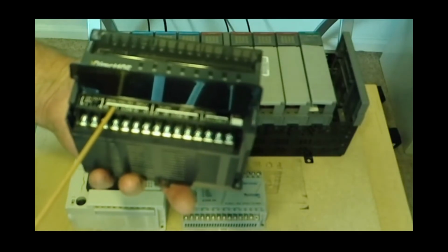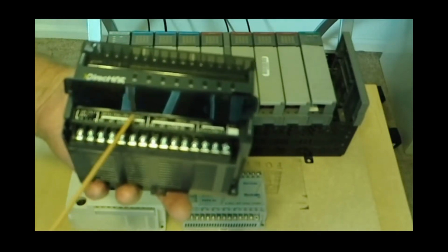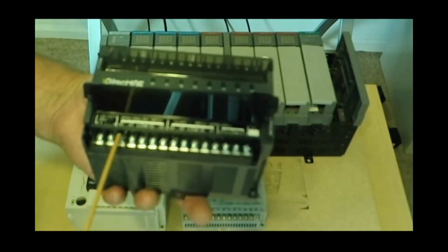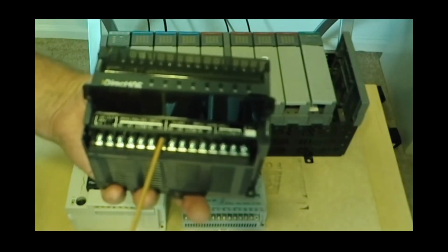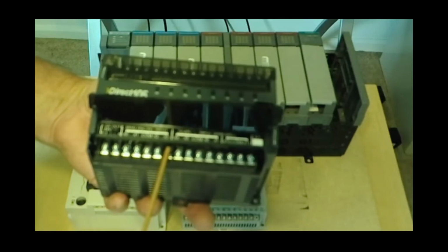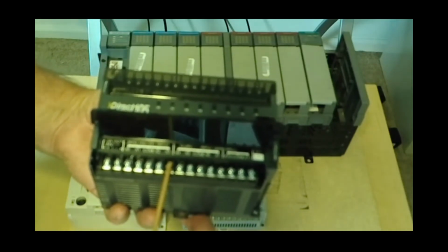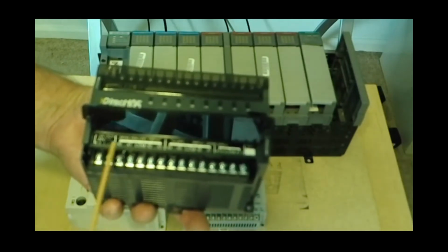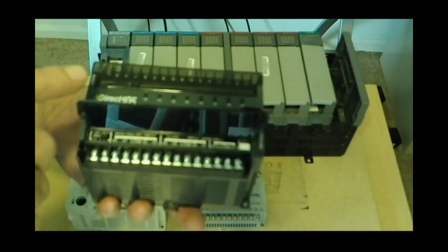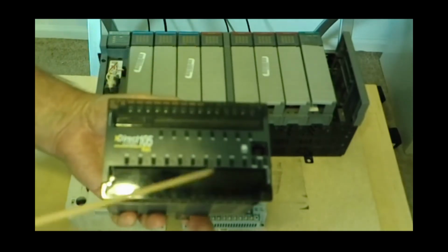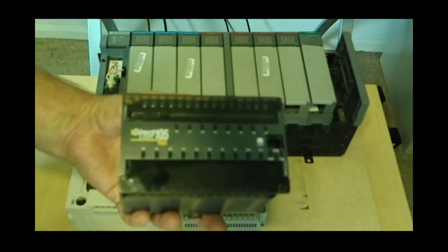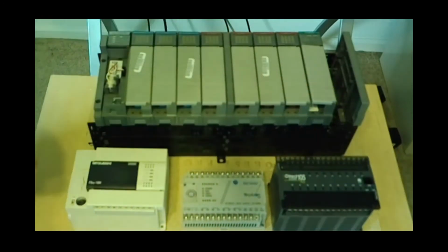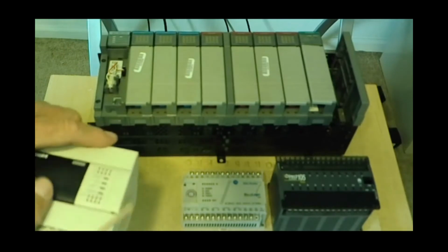Now the difference right here is these 3 terminals are identified as a high-speed counter input. What that means is these will count pulses, let's say from a servo motor, count pulses from whatever you can think of up to 5,000 hertz. So that's a lot of pulses, so you can count and measure with these. Or you can use them as individual inputs and outputs. So not bad for a processor. The last time I bought 3 of these, I paid about $95 a piece. So yes, you can get these things cheaper than the cost of a box of relays.